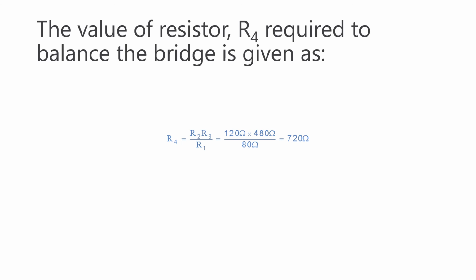As we have already seen the uses of various bridges, Maxwell's bridge is used to measure inductance in terms of known capacitance. It is preferred for low Q coils. Hay's bridge is also used to find inductance values, for coils with high Q values.